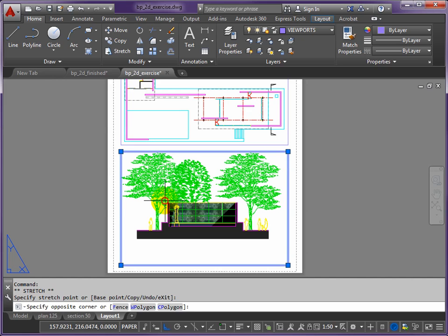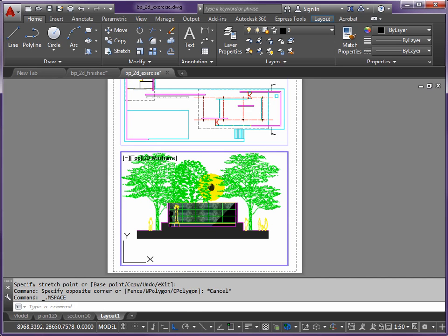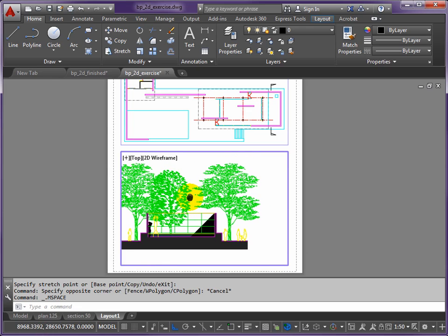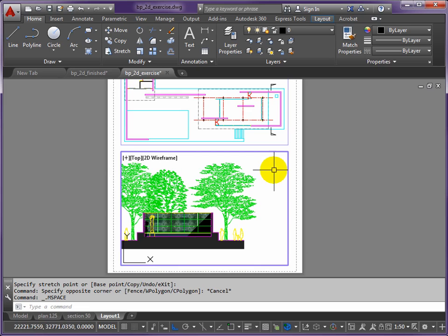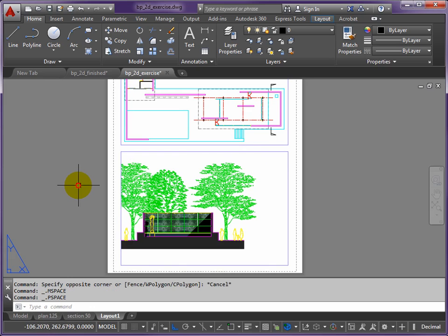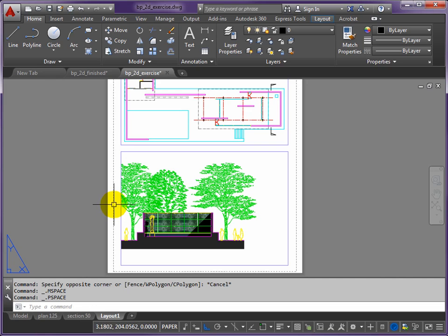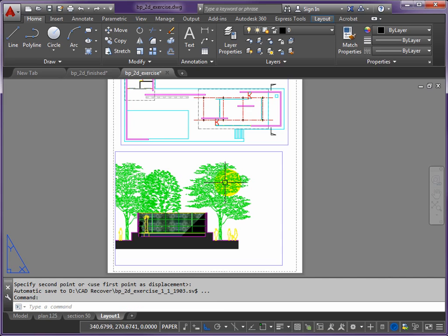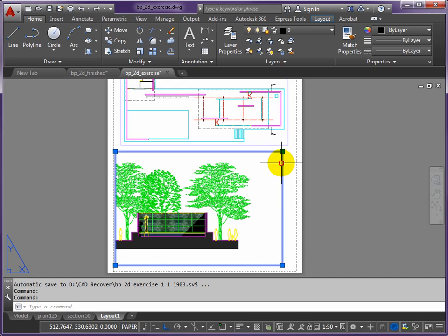Now go into the viewport and hold your middle mouse button, and we'll pull the viewport across. So I'm just going to tuck it to the side. Okay, I'm trying to end up with enough space over here to have the aerial site plan as well. Okay, so double click outside. We've got plenty of space here at the side. We could move the viewport across, so I can just create a bit more space over here. Click on the viewport edge, and let's bring that in a bit until it just clips the edge of the shading.